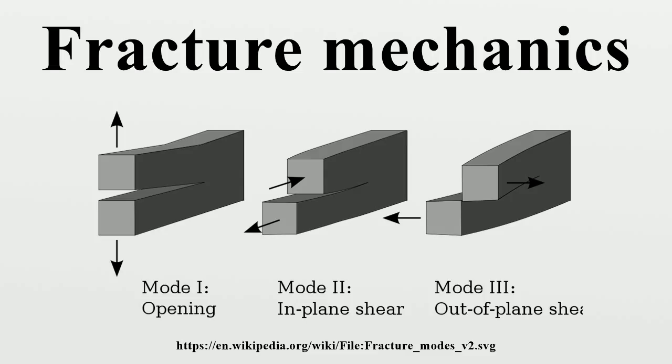Engineering applications. The following information is needed for a fracture mechanics prediction of failure: applied load, residual stress, size and shape of the part, size, shape, location, and orientation of the crack. Usually not all of this information is available and conservative assumptions have to be made. Occasionally post-mortem fracture mechanics analyses are carried out. In the absence of an extreme overload, the causes are either insufficient toughness or an excessively large crack that was not detected during routine inspection.